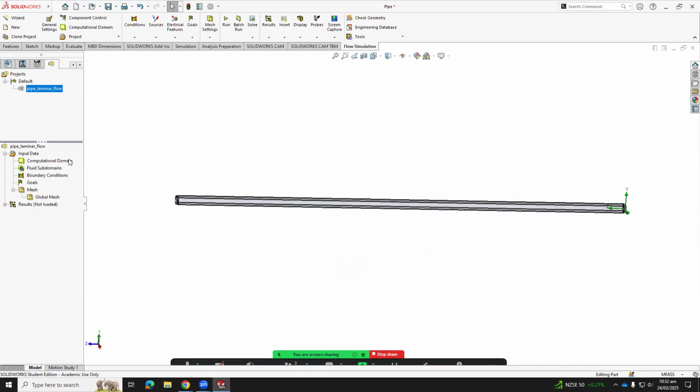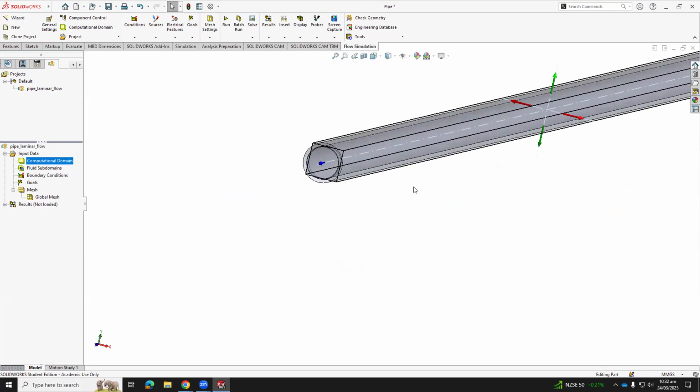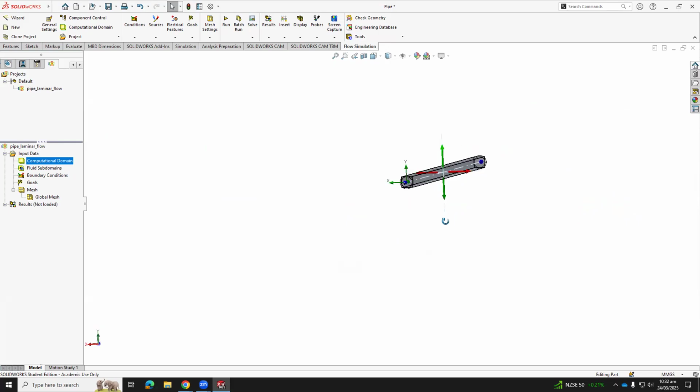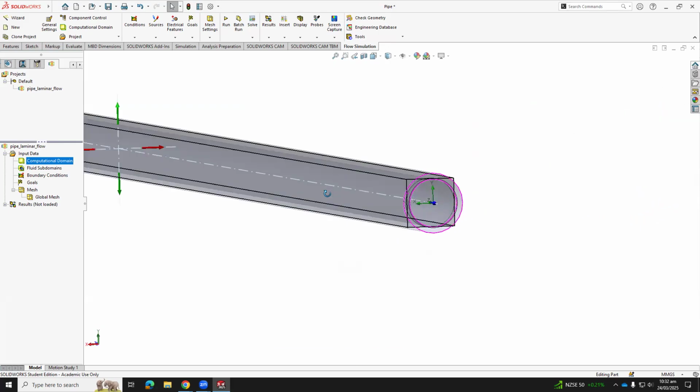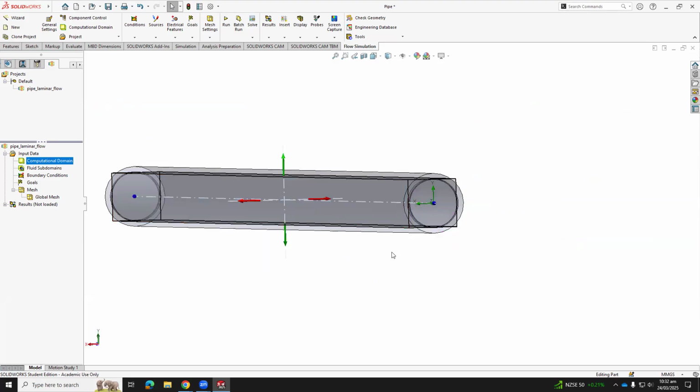Okay. Computational domain. What's computational domain? I need to explain this, very important for CFD modeling. When I review papers, if I see someone didn't submit this computational domain, I get really upset, even in your assignment. Computational domain is just to let the person understand where the fluid is, or where the CFD software is solving the problem.